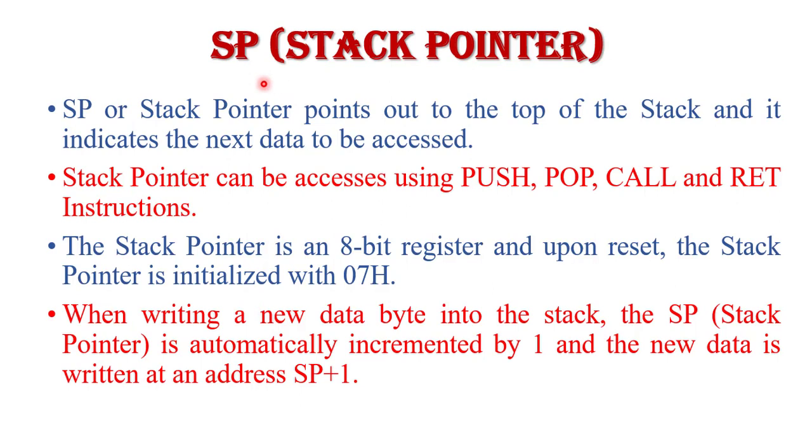Now next is the stack pointer register. Before I discuss the stack pointer register, first let us know what we mean by stack. A stack is basically a section of RAM used by the CPU to store information, such as data or memory addresses, on a temporary basis.